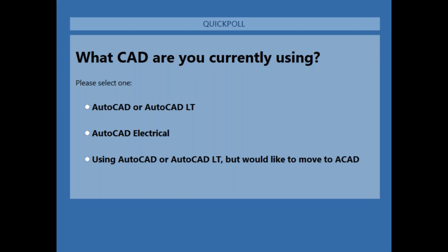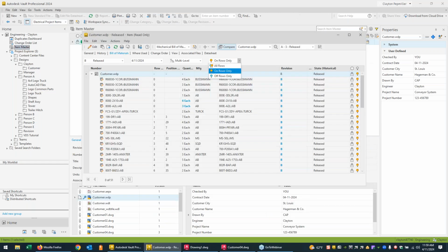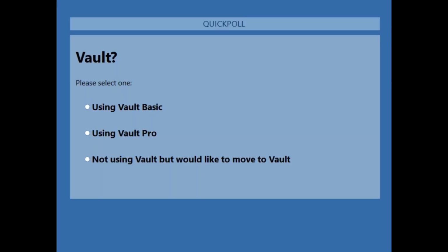Right. The other way, and the way that I've kind of done it in the past, is set up the network share, put everyone, aim the WD-ENV file at it, but then also take a zip file of the catalog and a zip file of the libraries and push those into the Vault for safekeeping, and update that file as necessary, at a quote unquote oil change frequency, every 3 months. I just opened up the second poll if you guys want to start answering that.